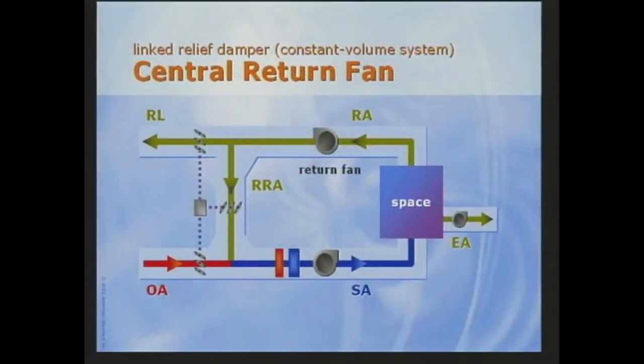The first is sometimes used in constant volume systems. It simply turns on the return fan whenever the supply fan is on. Both supply and return airflow are constant. Building pressure is not sensed. The outdoor, return, and relief dampers are usually linked and controlled by a single actuator. The system can be balanced to maintain a slightly positive building pressure in cooling mode. However, without direct control, building pressure may fluctuate widely in economizer and heating modes.